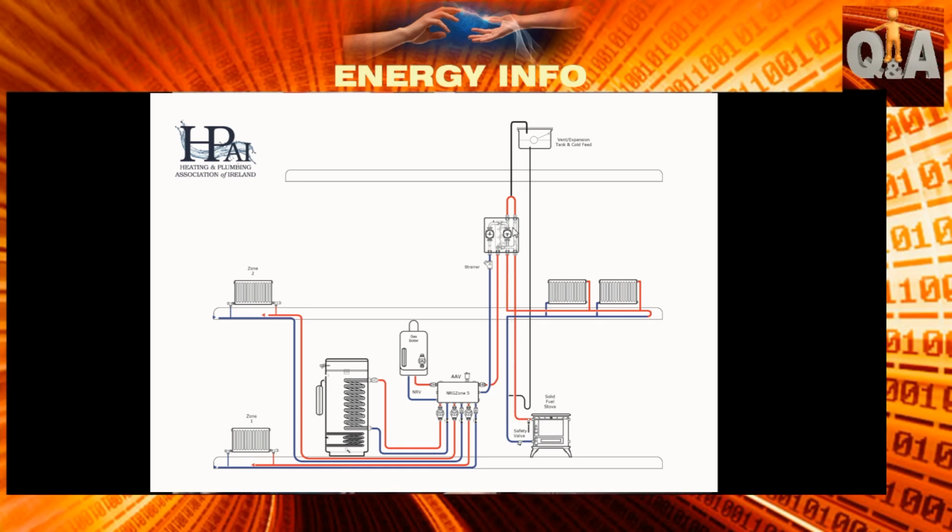Why do you go top and bottom with the radiators? With a heat leak radiator, it's critical that you get a good gravity circuit, and because the heat wants to rise, you let it rise into the radiator. As the radiators cool the water, it falls out the end into the return pipe and back in.